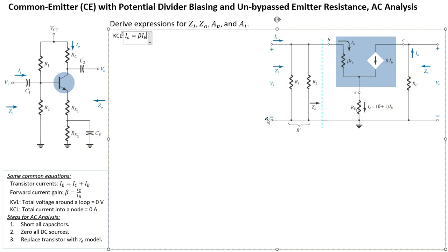Now let's have a look at II, but II is going to involve ZB. So maybe we should look at what ZB is first. For ZB, we're going to use Ohm's law and KVL. So Ohm's law for ZB, R equals V over I. So V is the voltage across here plus the voltage across here.